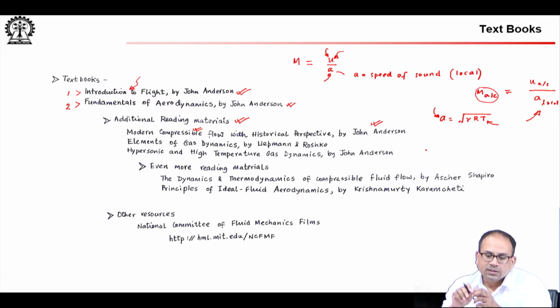So, your operator is interested in some aspects, interested in the time from A to B. So, he is using the ground speed and the distance between A and B, whereas for the fluid mechanical behavior around the aircraft as it is moving through the atmosphere, we see that different characteristic phenomena start showing up at different Mach numbers. So, here ground speed is not important.